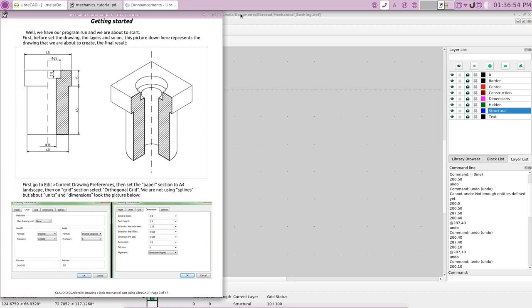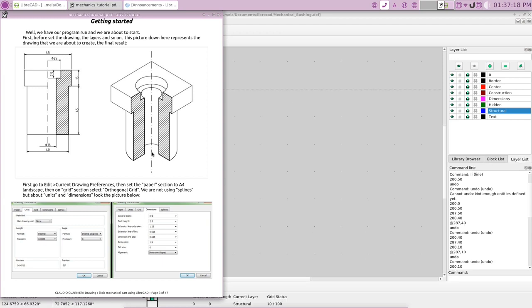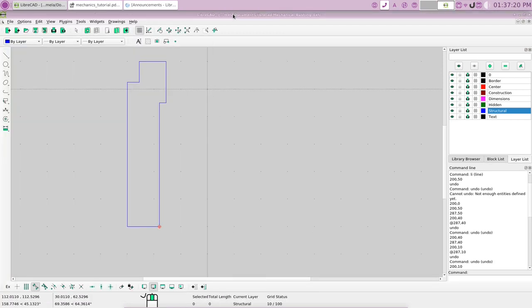So what we can do here is, this is the diameter of 25, and this inner one is a diameter of 16 units. But the center line would be half, it would be a radius. So the radius is 12.5 from this edge to this line. And the radius here is 8, half of 16 over to the line. Okay, so let's do that to find the center line.